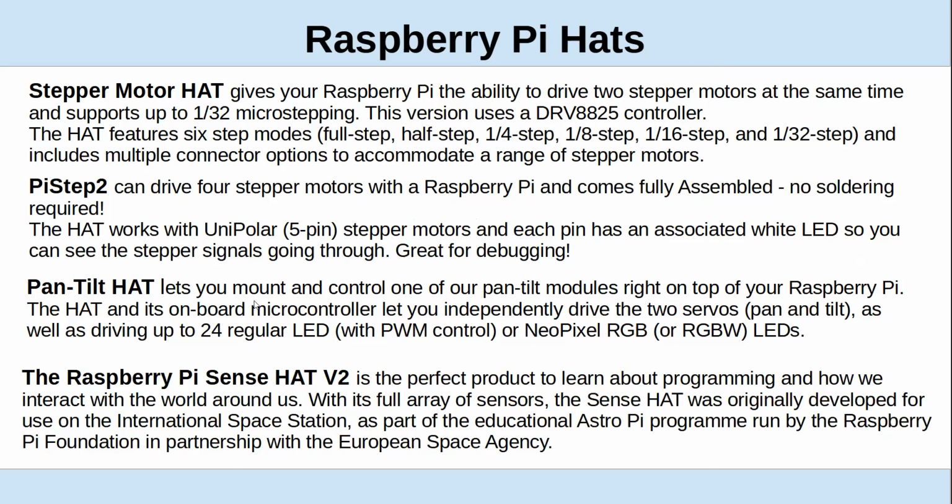So stepper motors, what are some common numbers of steps on a rotation? 200 steps per rotation typically. Now you can get them at 400. So it's either 1.8 degrees or 0.9 degrees.